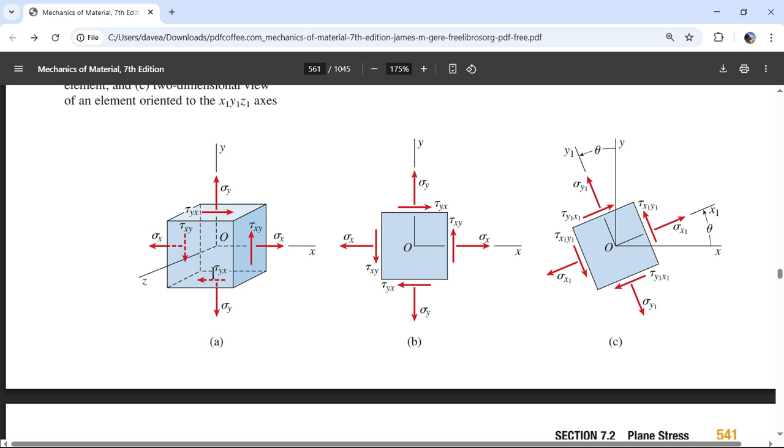So with that initial example of a 20-degree angle here, knowing that this surface area got greatly reduced, we still have a value for its pressure, so we can find its force. If this is force divided by area, we know the area, so you just multiply those two. So this times area is a force, and using a free body diagram, we can figure out what this shear force is and this normal force, and we know the area. So I could find those two. Even though we have 8 things going on here, we only need to find one value of shear using this new angle.